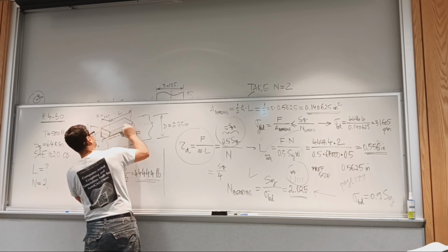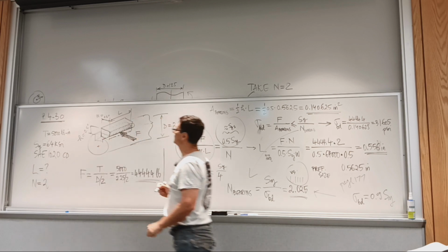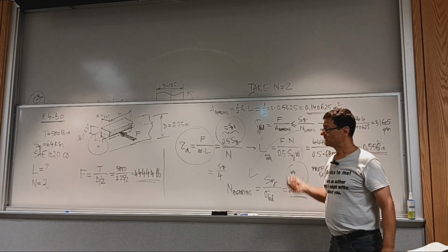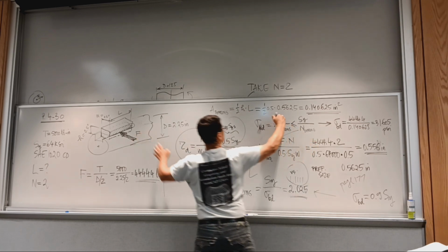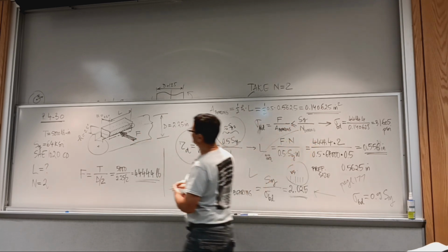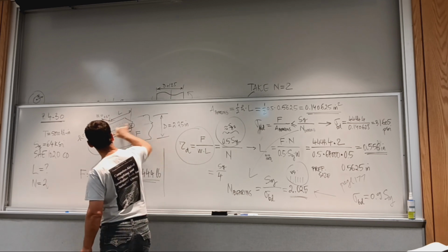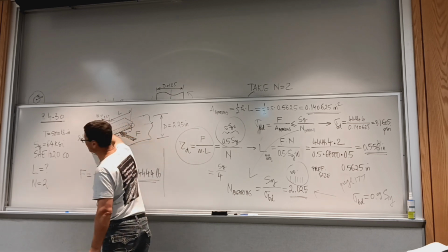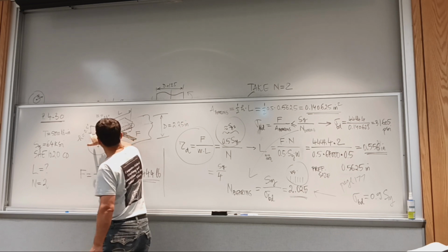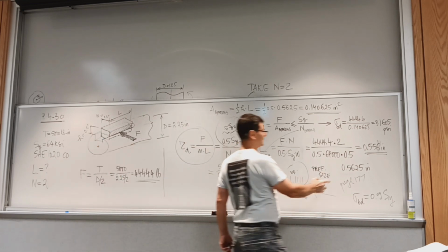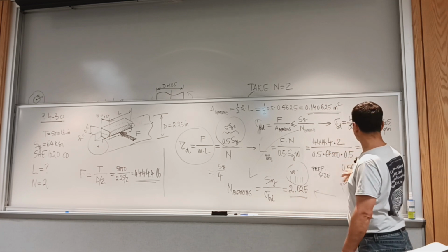So this is the bearing area between the hub and the key. And you evaluate the bearing stress by dividing the same force by the bearing area. And the bearing area is the same length times half of the height, up to 0.625. I think this is where they switch to flat keys.